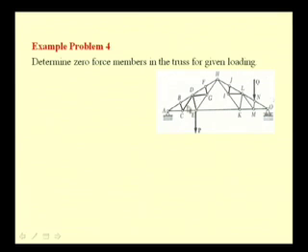If both DC and DG are zero force members, then obviously this member DE has to be also a zero force member, because any force in BD is balanced by the force in DF, but the force in DE cannot be balanced. So, we see that these members DC, DE as well as DG are zero force members.